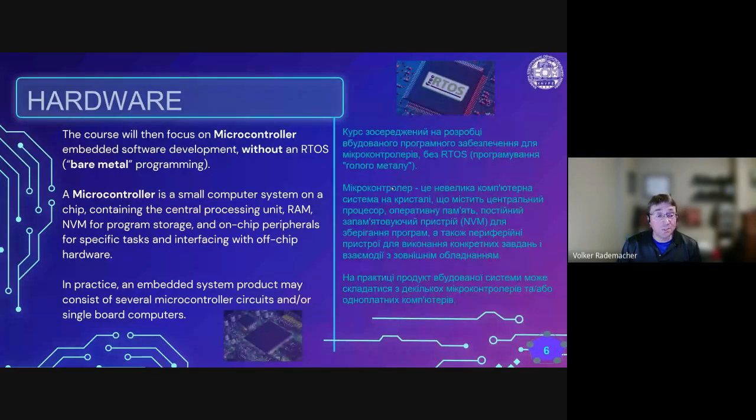It is actually now also common for the processors in single-board computers to contain multiple cores of different types. Some of the newer microprocessors contain inside the microprocessor a core for a microcontroller. That happens for exactly that reason, for real-time operation, to separate those two issues.